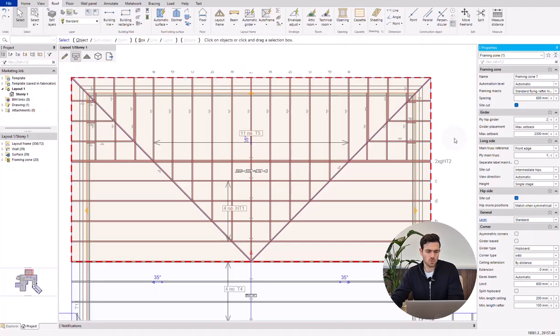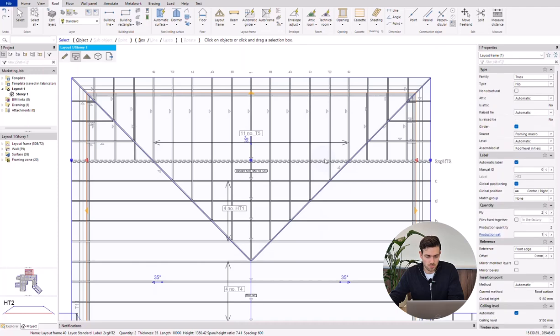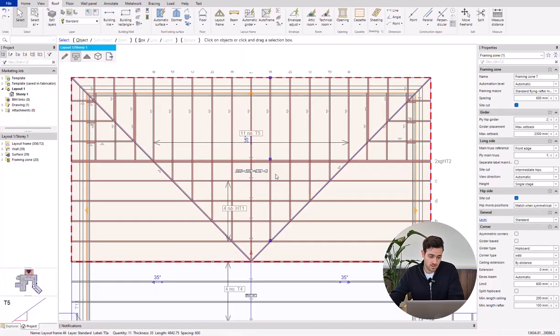And we now have some more options on how far back we can set that girder. Moving the girder back is going to increase the truss height, which is really useful because a shallow girder behaves more like a beam and it may require extra plies. Increasing the setback gives us the extra height needed to potentially avoid that.